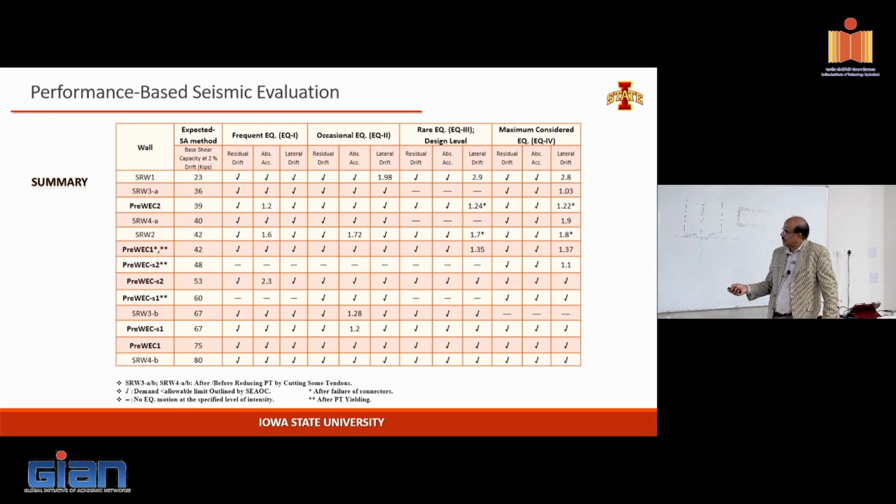So you just eat away the energy, and that's what dissipating energy is. For the 18% damping we put in here, you can argue that it improved performance, but it's not day and night difference. It shows improvement. So my argument is that, okay, maybe this is not enough, maybe this is better, but maybe we don't need 18%, maybe we put in 12%, this should be good enough. You take a non-seismic case, if you say you want to put in a strand and no reinforcement in the panel, I don't think anybody will approve it.